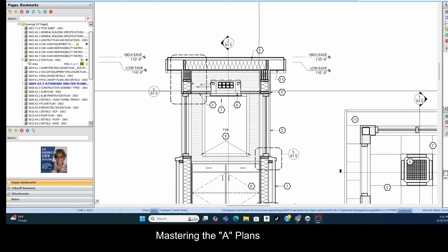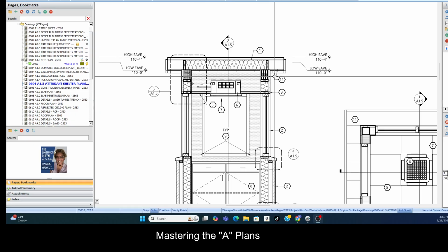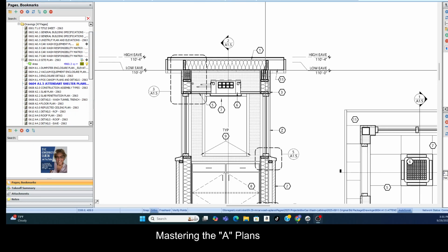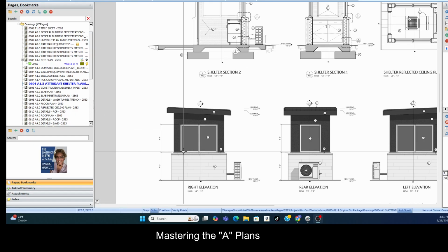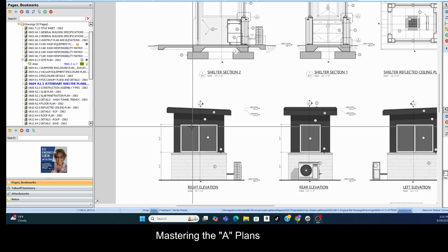Because this portion of the project is a structural component. Anything above an opening, whether the opening is a window or door, is part of the structural component. This is the header, right? So, for instance, you're going to have a header all the way across here. Anywhere you have an opening is the header.